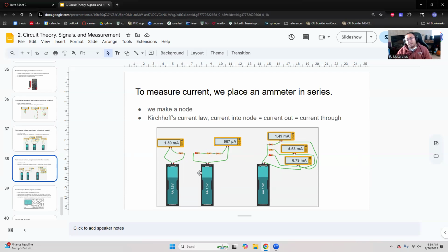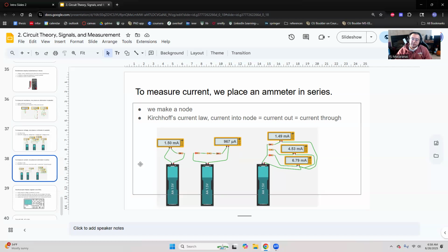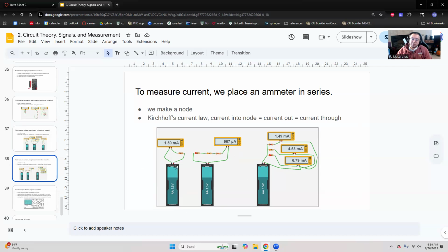And in this middle example, I walk out of the battery, and then from there I go straight into the ammeter, out of the ammeter, back into my network of resistors there. Right. And so, like I said, it doesn't matter if you come out of the battery into the ammeter, come out of the resistor into the ammeter. All of these currents should be the same, right? Because I've got a single loop.